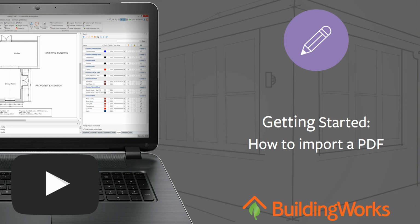Maybe you want to import a PDF of some plans so that you can trace the plans and estimate the job in BuildingWorks. Or perhaps you want to import a PDF map of the local area to show your building in situ. If a DWG or DXF version of the file is available, you might want to import that instead. You'll be able to interact more with the imported drawing, for example by clicking on snap points. With an imported PDF, the drawing will simply appear as a symbol. In this video, I'll show you how to import a PDF and how to place the image on your drawing.